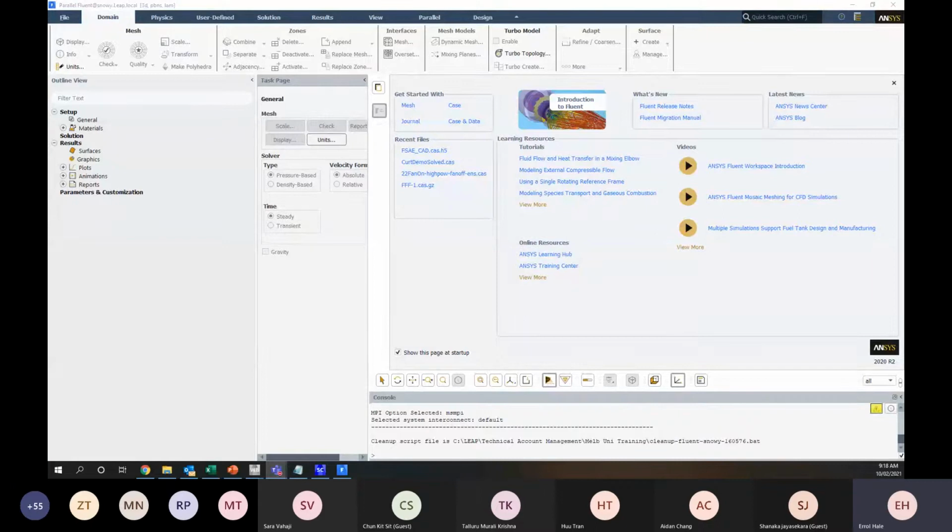Usually we'd be going for a more refined mesh, and solving the model again. What we're looking for is good convergence behavior, so a high quality mesh, and also for our solution variables, things like our lift or our drag in this case, to not change with an increased mesh density.